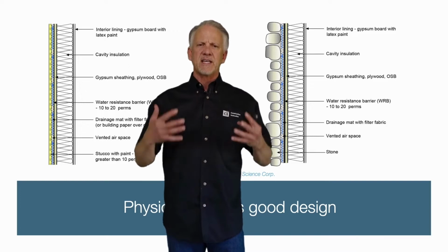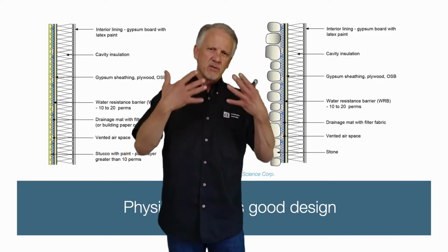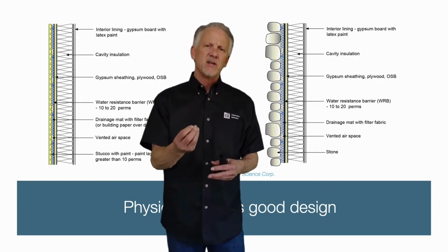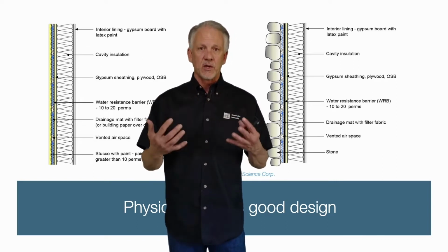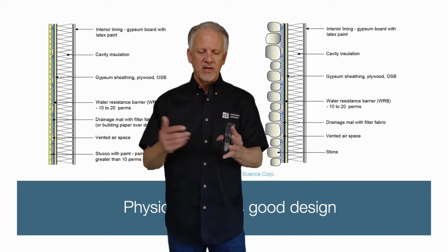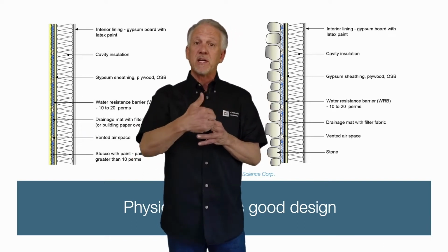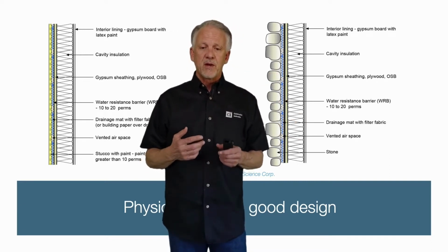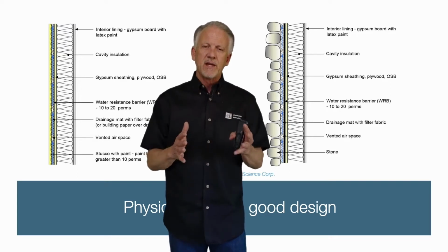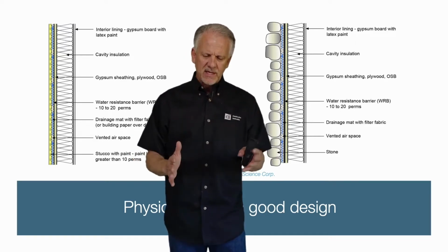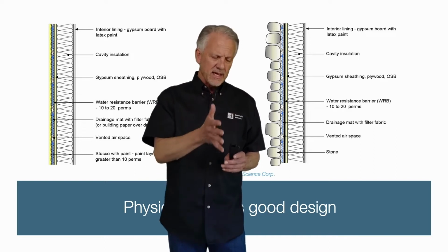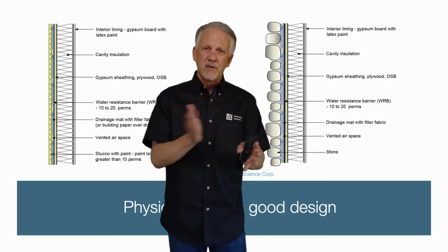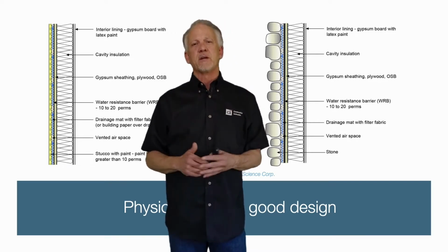Think how critical that is to get that liquid water away and let whatever water is stored within the cavity, or the assembly, I should say, that it can then dry more quickly using airflow, or letting the sun do that without having it driven back further through the assembly, potentially into the sheathing or into the wall cavity, which would be even more detrimental. So I think the strategy here is that we look at how building assemblies are put together, how we look at things like vapor drive, reservoir claddings, drainage systems, and products that inhibit or reduce the flow of this moisture through the assembly. All of these are critical components.